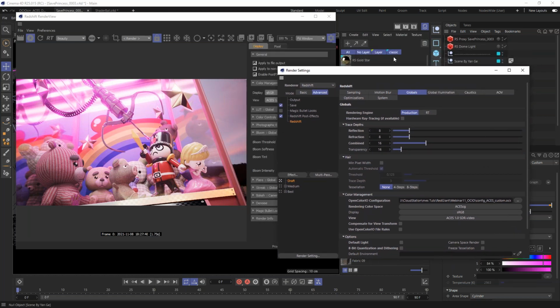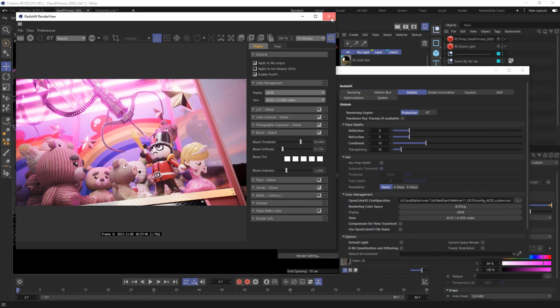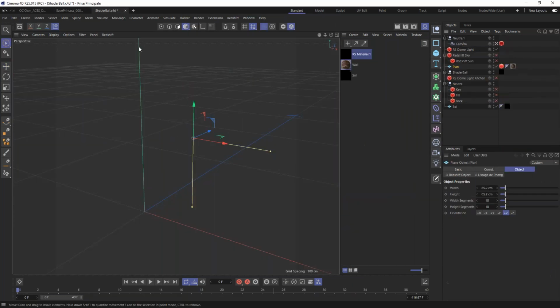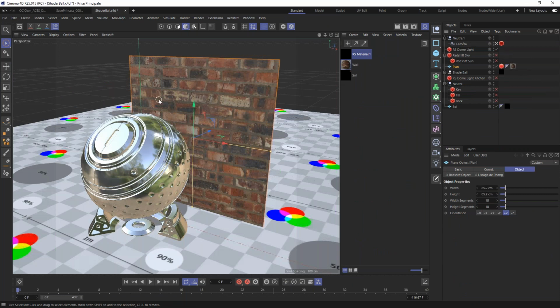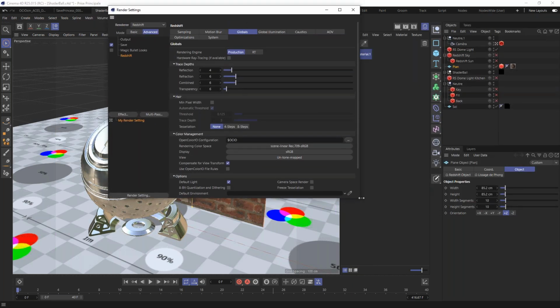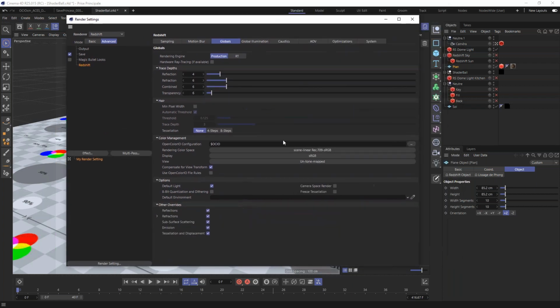All right, cool. So let's stop that and see a very important subject. This is an old file, and I just left it as it is because it was made about six months ago. You can see the rendering color space is linear Rec.709 with no tone map. This is normal. If I want to convert it to ACES, I need to choose ACEScg and then here ACES. That's all you have to do.